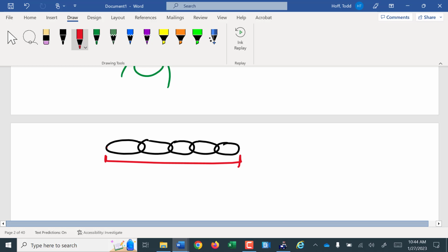And so you'd go section by section on the parts of the chain that you know are going to wear faster. The parts that are bending like that, or any part that, if you have a rigging where you have to push it off to the side and lower it, the part that's going to flex when you have to move off to the side, that part you're going to measure on a smaller scale to make sure that you don't have excessive wearing there. Because I've seen chains where the total elongation of a 15-foot chain is within specs, but there's individual links that are nearly worn through because they're the ones that were getting all the friction.